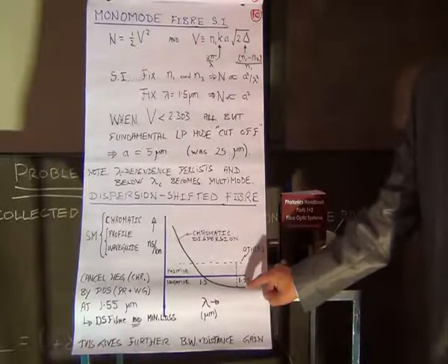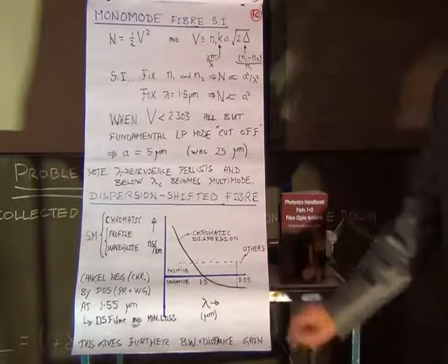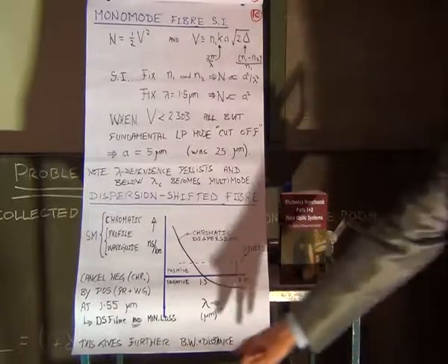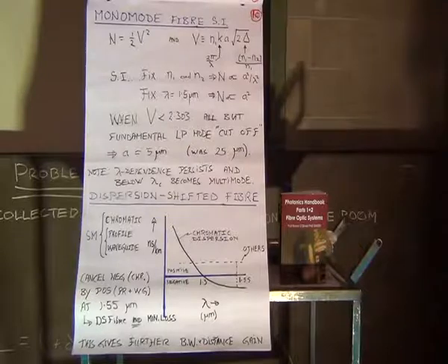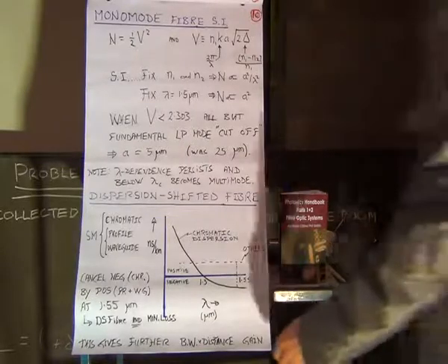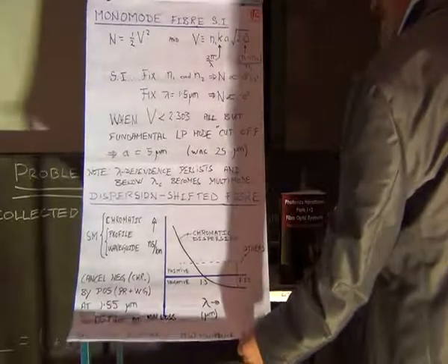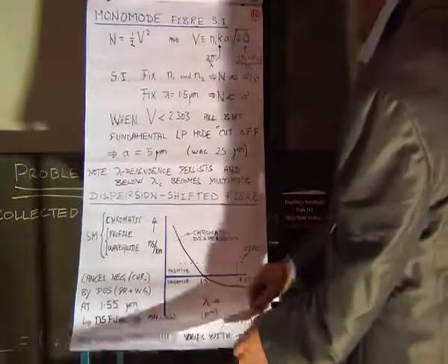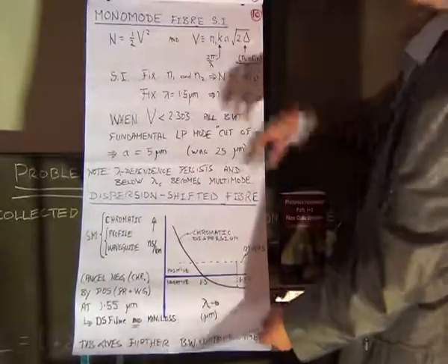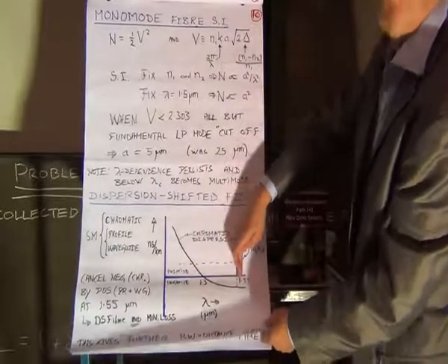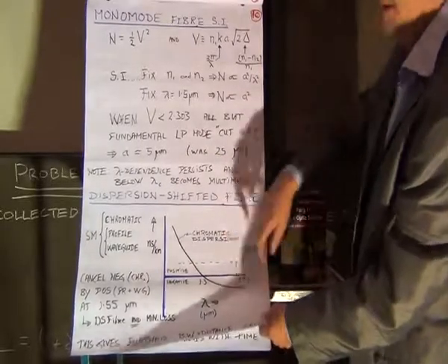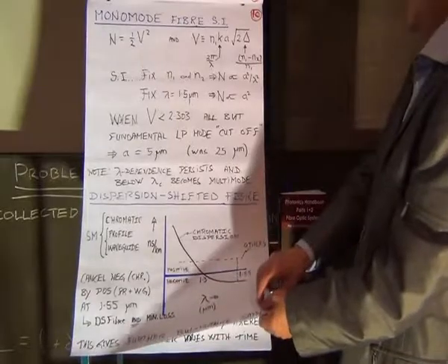That would seem to give us the ultimate optical fibre, the greatest bandwidth distance possible. So we call it dispersion shifted because we've shifted the dispersion minimum out to the loss minimum. We're getting both effects at the same time.